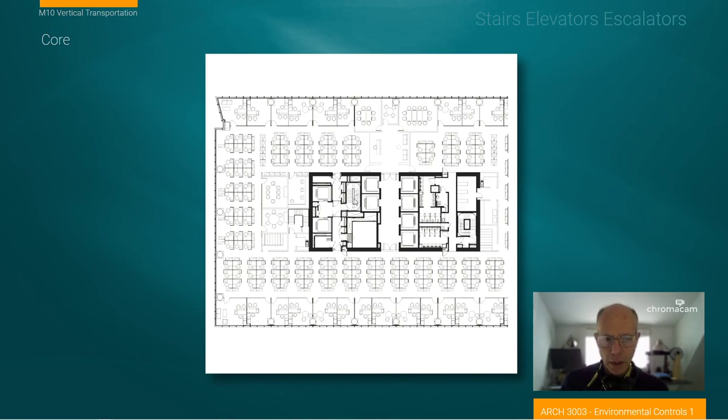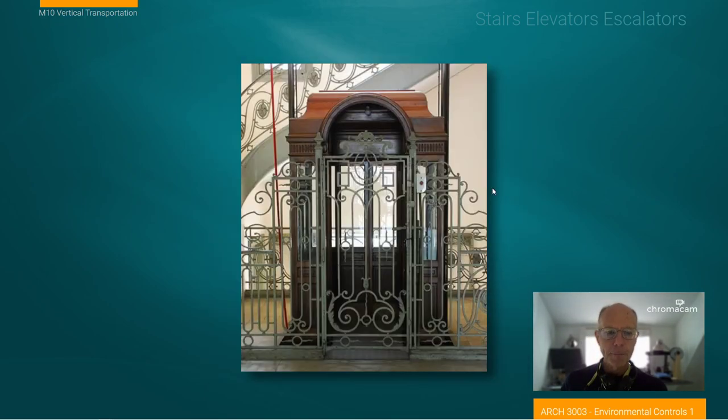Typically then with our egress stairway, we have 2 stairways that allow us to get through the building in the event of a fire and the failure of our elevator vertical transportation system. So those overlying concepts, this idea of core and the centralization of these functions to stiffen multi-story buildings, is a critical understanding going forward for architects thinking about designing building systems.